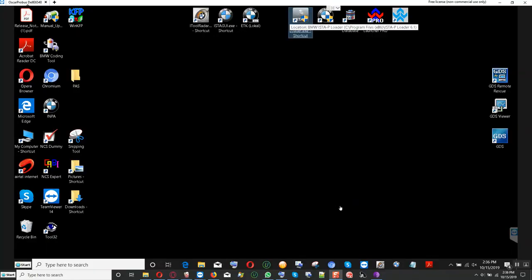Alright, okay, YouTubers. We can't do any more with the E70 here. There's a problem with it. He changed the DME and it's used. He said the car starts and so on, but somehow when you read out the vehicle order, it comes up with a conflict that it can't read out the vehicle order. Either the CAS unit and the FRM are corrupted or both control modules do not show the same vehicle order, okay? So, end of this session for now.